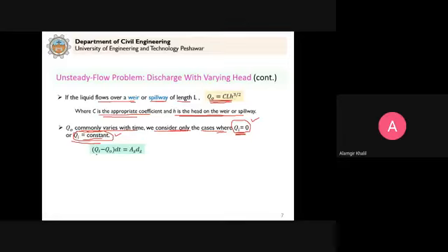So now we come back to this equation. Now we are clear about all the terms. This is the change in water level. This is the surface area, no problem. This is the time dt. And now we are clear about Qi and Q0. So what we can do is write dt equal to As dz divided by Qi minus Q0.